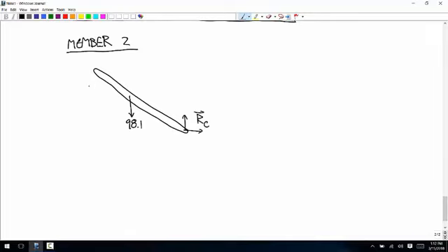Okay, and then what's happening up here? This is the most complicated part. Always the most complicated are the joints where the 2 members are in contact. Well, the pin is part of member 1, so that 500 Newton force is not applied here. But this member does touch the pin, okay? And the pin is part of member 1. So there's a force on 2 by 1. If we called this variable the force on 2 by 1, we would have 8 variables in our system. We'd have the variables RA, X and Y components, F12, X and Y, F21, X and Y, and RC. And we wouldn't be able to solve it. But Newton's third law says that F21 is equal to negative F12. And so we're going to write this in terms of a variable we've already defined, and then we only have 6 variables in our system. Okay? So that's a key part of this.